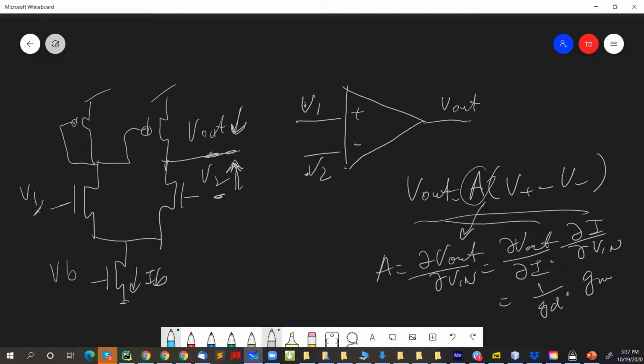So in subthreshold, you already know what it is. You know that in subthreshold, GM is kappa I over 2 UT, and GD is the drain conductance of both these transistors. And so you can essentially write it as kappa VE over 2 UT. Any questions? Then you can do the same if you want to compute what the gain would be when operating above threshold.